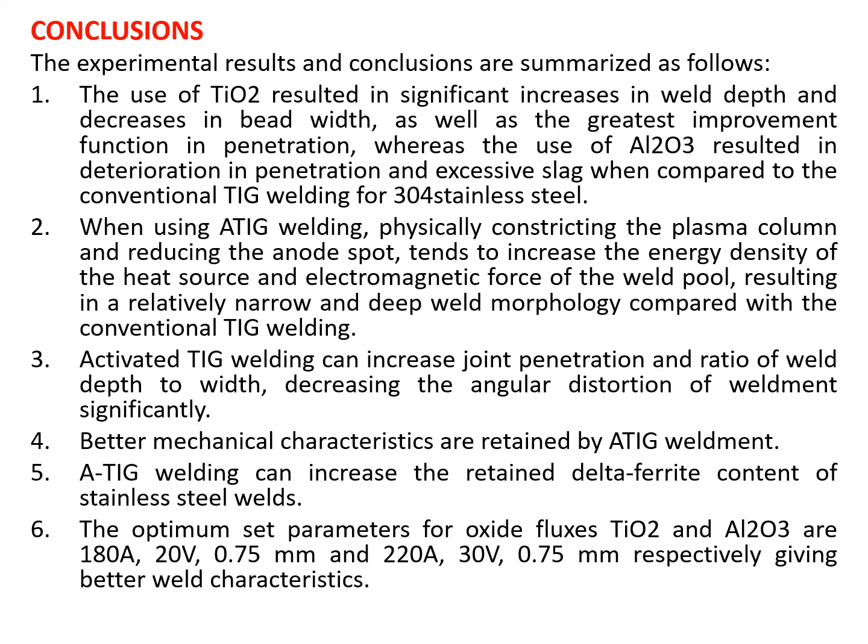The optimum set of parameters for oxide fluxes TiO2 and Al2O3 are 180 ampere, 20 volts, 0.75 millimeter and 220 ampere, 30 volts, 0.75 mm respectively, giving the better weld characteristics.